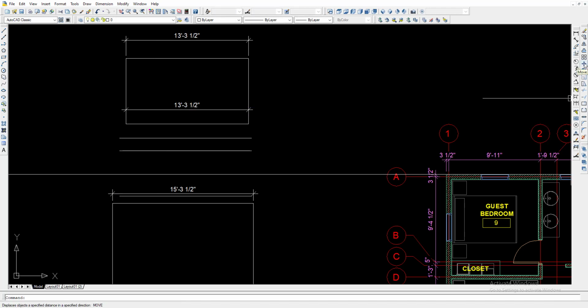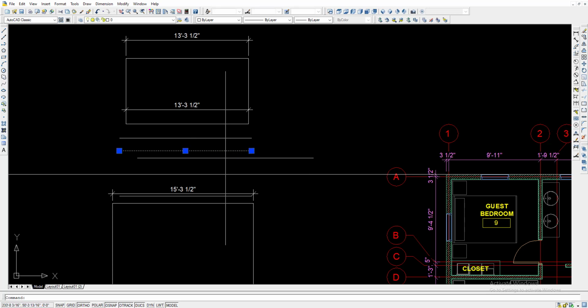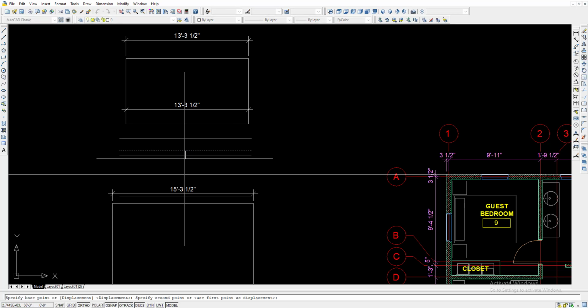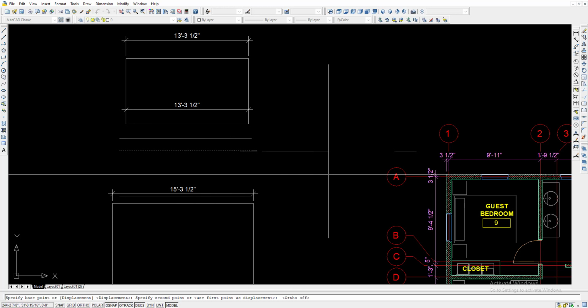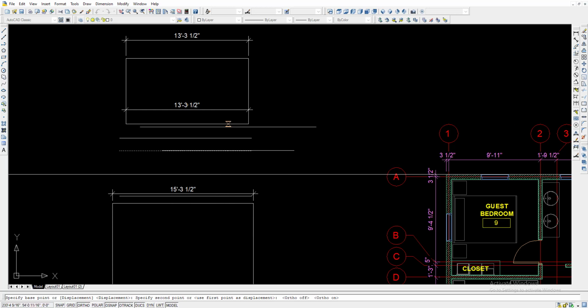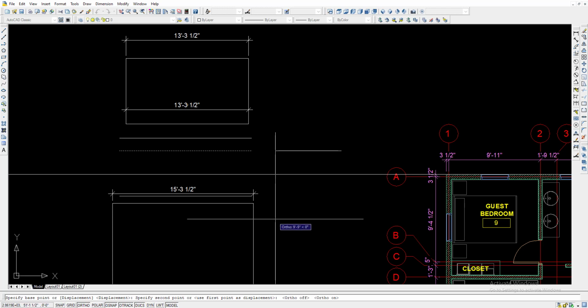Okay, here is another effective tool, move. If you want to move this object, then just click the object and click the move button from the left side. Then you can move the item from one place to another. Here you can see the other things: one is straight moving, just horizontally and vertically, no angular or inclined.